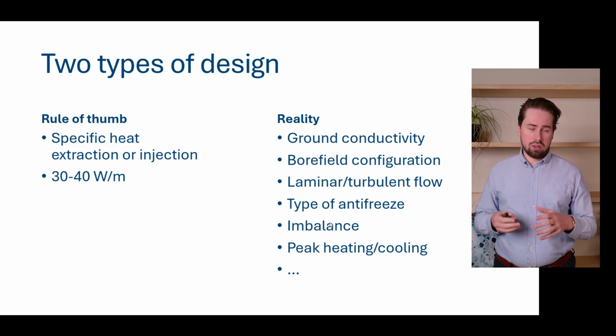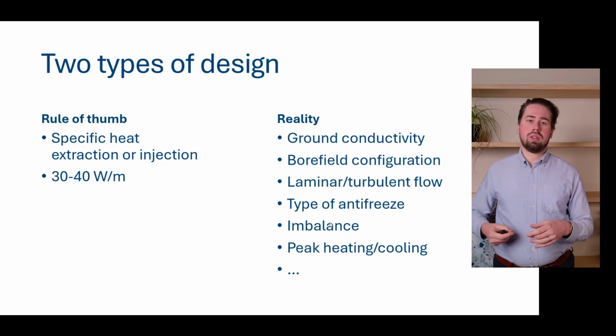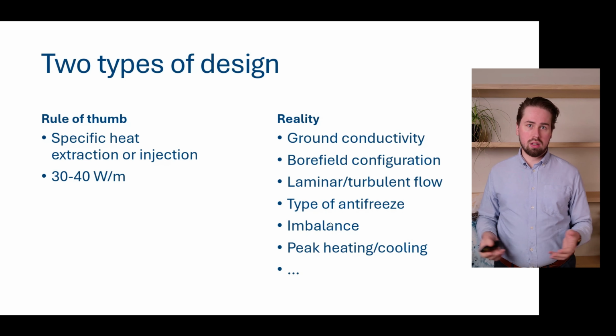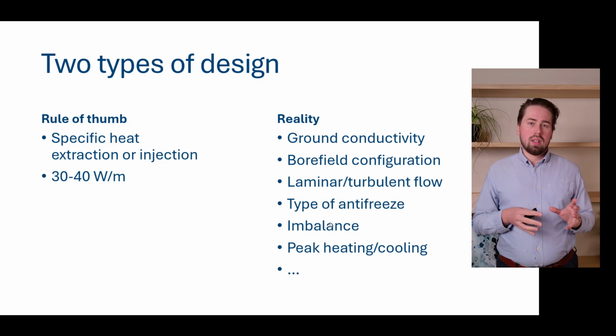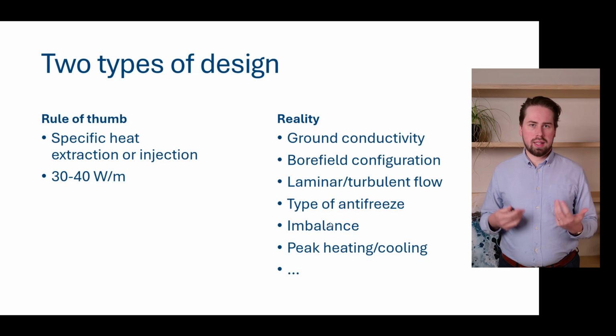If you do that and you know your peak power of your building, for example, it's 3 kilowatts, then you know, well, we need 100 meters of borehole length in total. So that's the rule of thumb. And on the other hand, we have what I call reality.